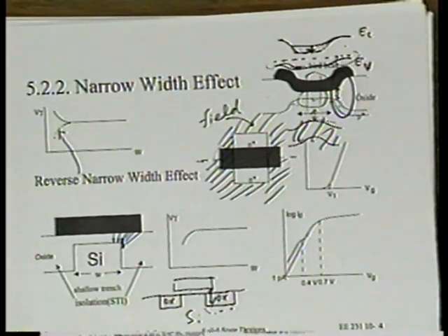You know, some people like to say it's because the oxide here is thinner, and they even point out a very correct fact, that is because of the oxidation rate dependence at the corner of a trench. The oxide thickness indeed can be and may be a little thinner than in the bulk, but that's not the correct explanation for why VT is lower. The fact is that the thinning of the oxide is very much minimal these days. The engineers try very hard to reduce the oxide thinning at the corner of the trench isolation.